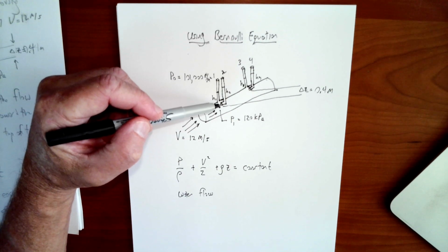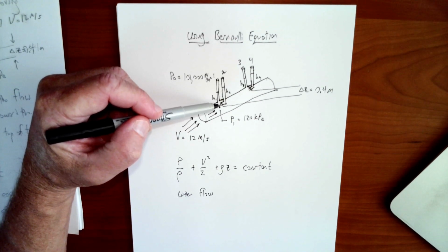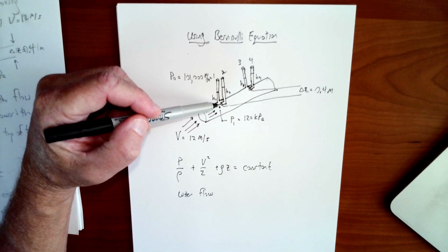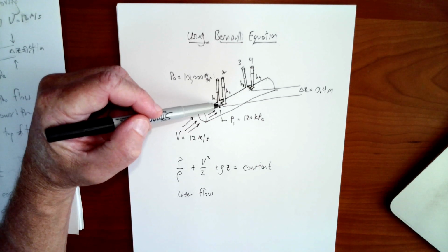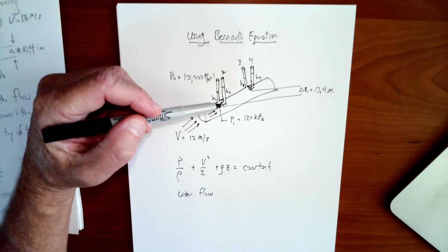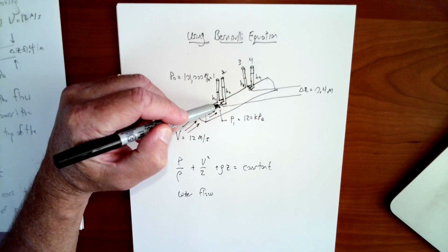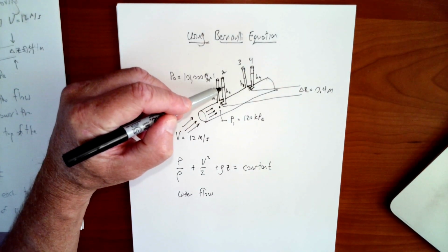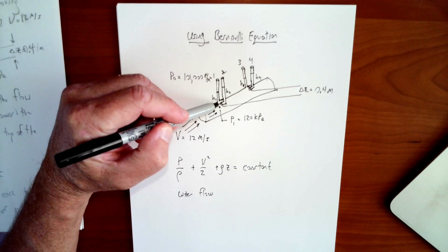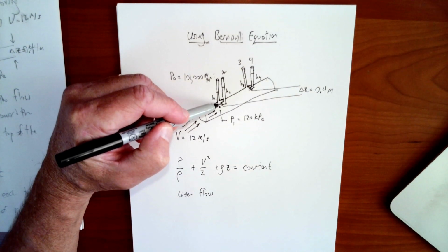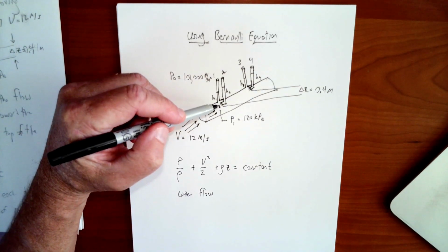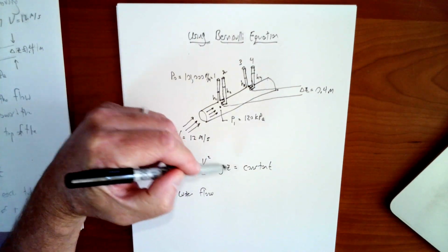This pipe, as you notice, very intentionally drawn so that its inlet opening is facing the direction of flow. So the velocity of the liquid that's going to that pipe is going to be reduced to 0 right in the entrance, right? Because the flow will reach some height here and then it will stop moving. So the fluid right at the entrance to this little pipe is moving at 0 velocity. And so that's going to cause a change in the measured pressure. We'll see that as an effect of the Bernoulli equation.